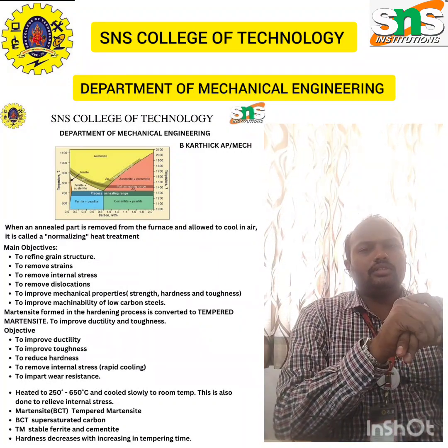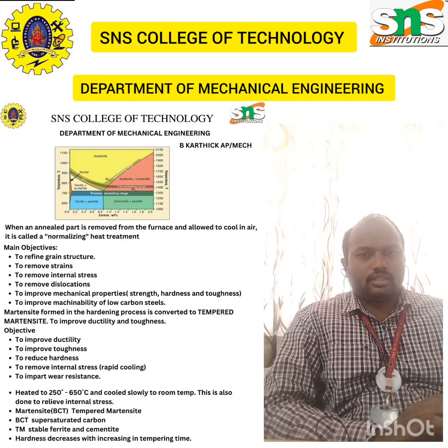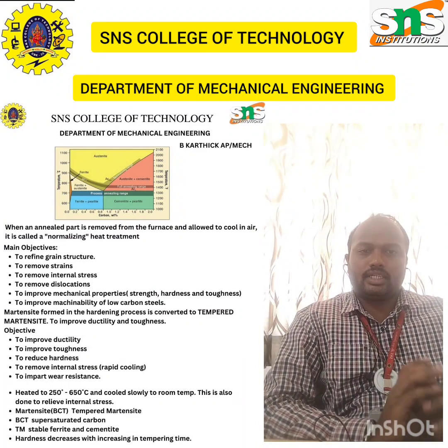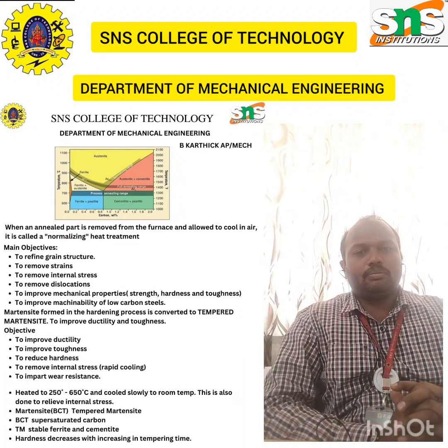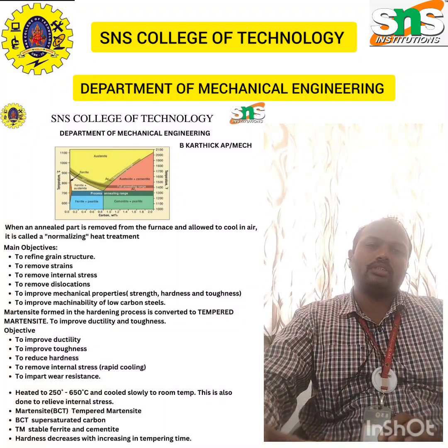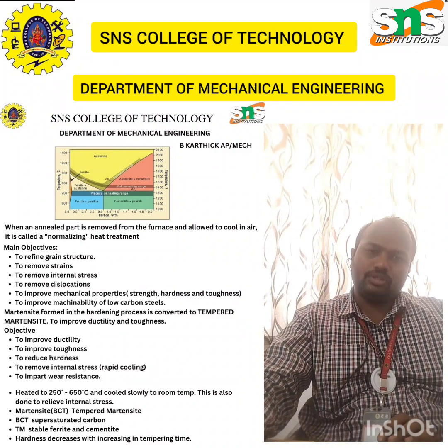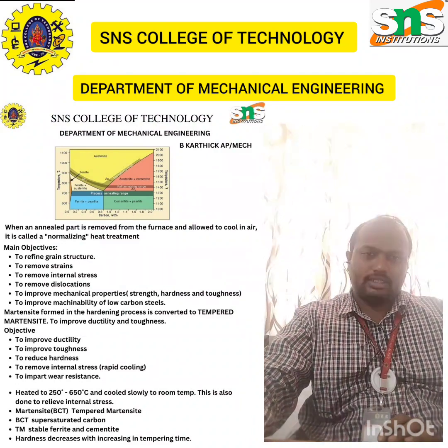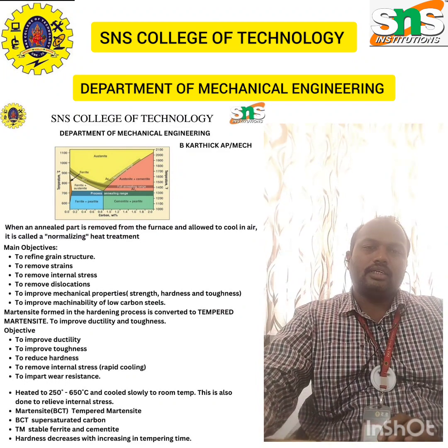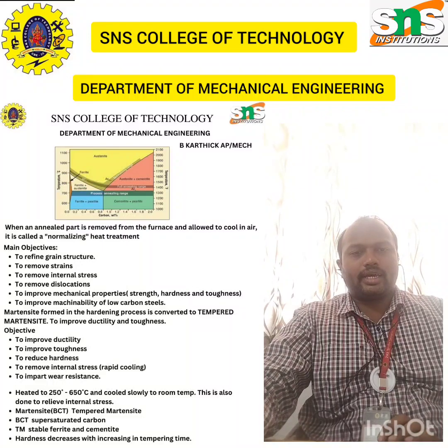So this controlled heating and cooling helps to relieve the internal stress in a material. For example, if we are doing a forming process or hammering process, due to the sudden impact or the loading on the material, internal stress is created. This internal stress has to be relieved, in order to avoid cracks occurring on the material.